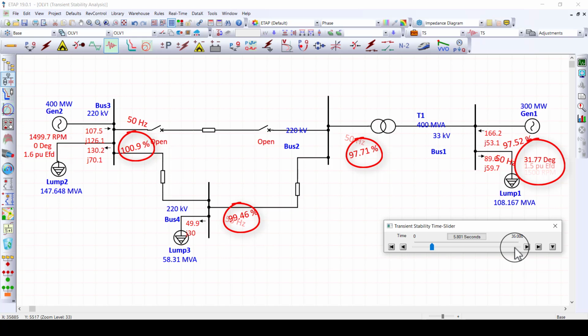So the power angle is increasing, and in the same way the output power is increasing to finally maintain the synchronization of the generator by maintaining its rated speed at 1500 revolutions per minute, and this is to maintain the rated frequency of the generator at 50 Hz, to maintain the synchronization of the generator with the rest of the system we have.